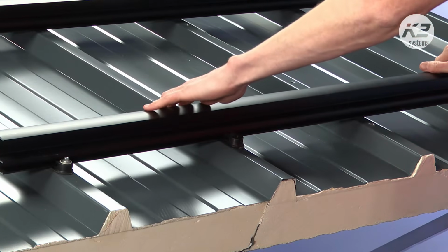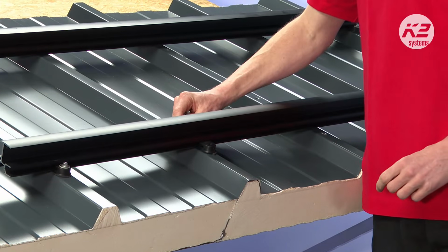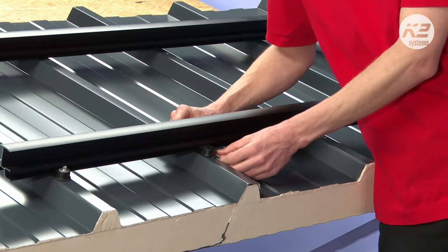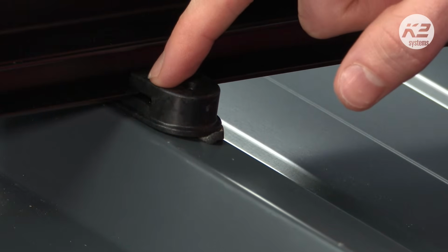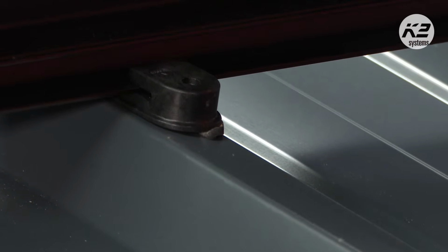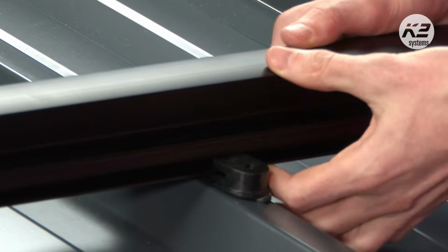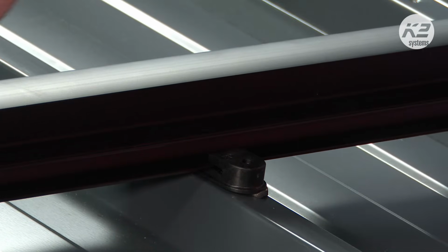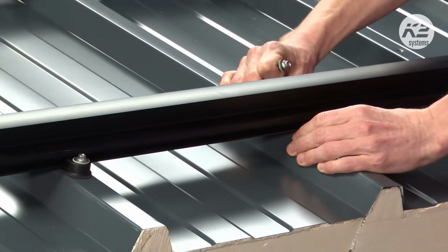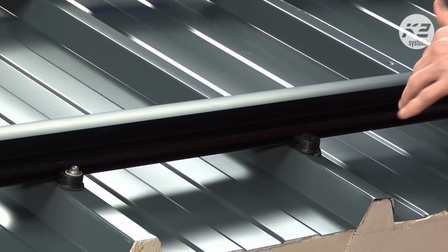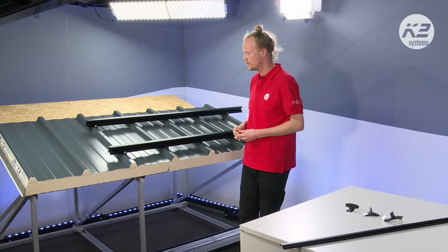So initially we started by pulling the rails down, sitting in the bottom half of this one, and on the middle one we've faced it the other way around. And Klaus, I'm not sure if we didn't test this before, but maybe you can see on here that there's a little gap on this top part, right? So this basic clip is pulling the rail down effectively, and the basic clips on the end are holding it up. And this is more or less how the system is now secured from moving up and down. So we have a vertical fixing, more or less, with this methodology.